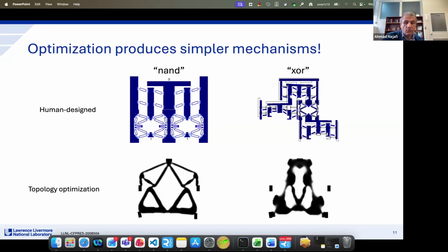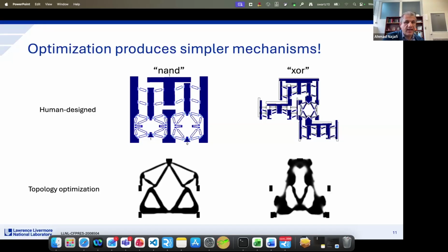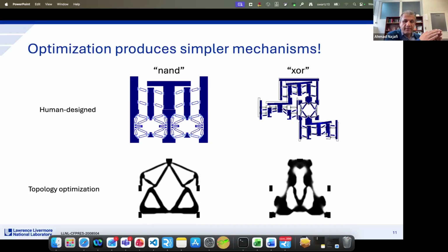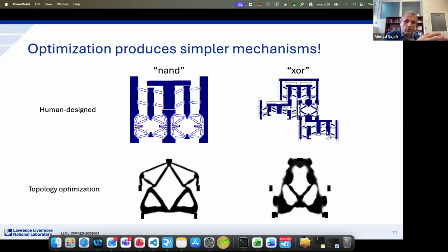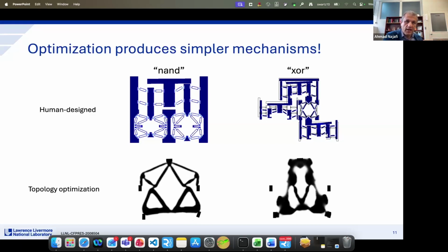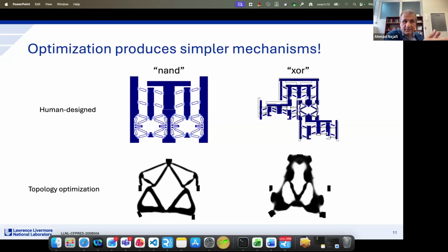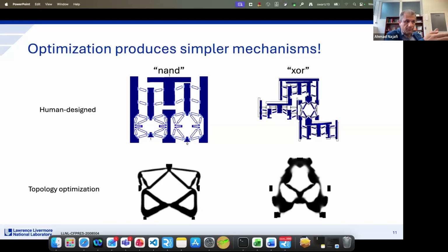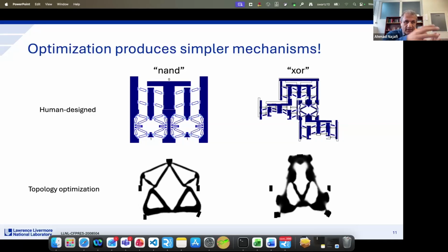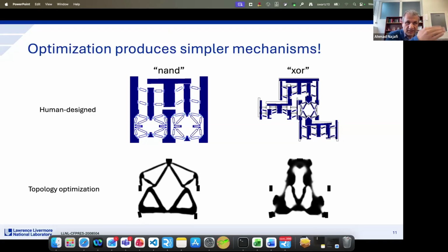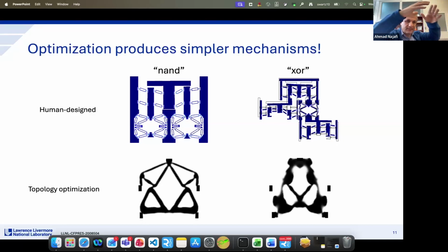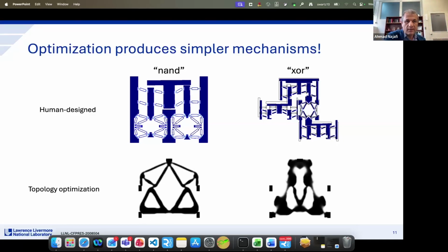Okay. While we are waiting for a new question in the chat: when you were mapping from 2D to 3D, are you allowing your topology optimization to change the layout in the third direction? For example, in the cantilever beam, if you go from 2D to 3D and allow the design optimization in the third direction, the design will change based on removing or adding material in the third direction too. What is the case here?